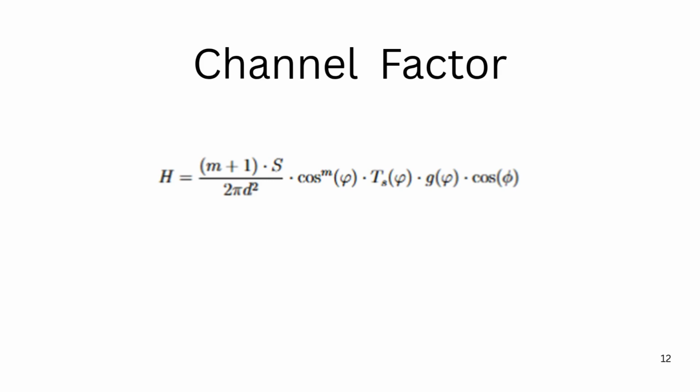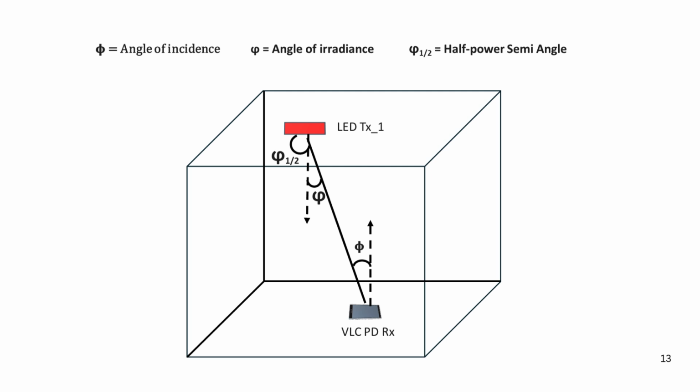Now, after setting up the transmitter and receiver, if we want to calculate the visible light channel between an LED transmitting data packets in a clear, line-of-sight scenario with no blockage from the surrounding environment, the channel attenuation of the LED-enabled visible light signal is formulated as follows. The given analytical expression of the visible light channel is derived by using analytical geometry but can also be evaluated by vectorization. Also, you can see the angles between the LED transmitter and receiver in the figure. This is how we calculate angles between the transmitting node and receiving node.